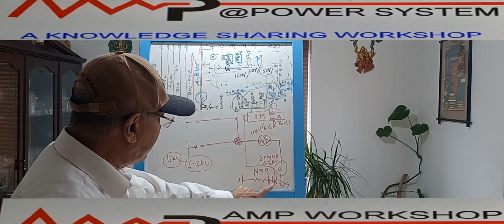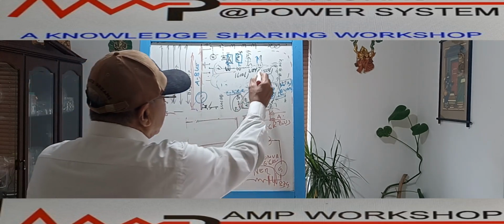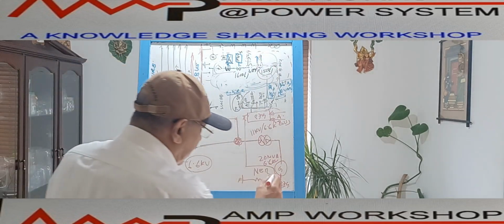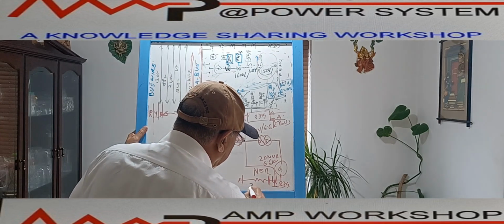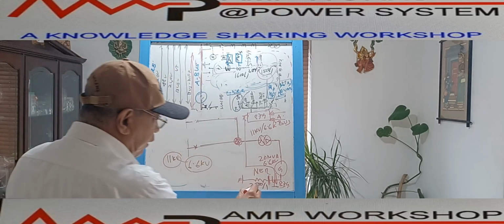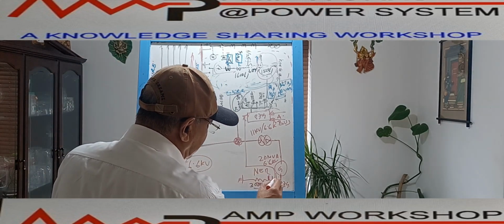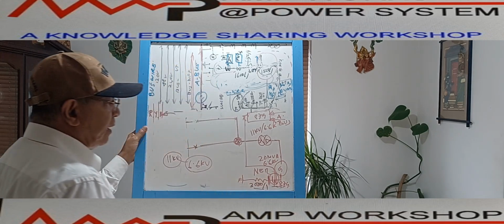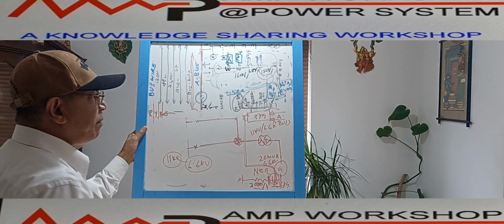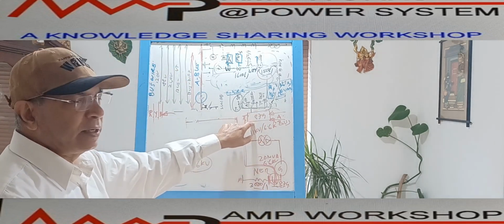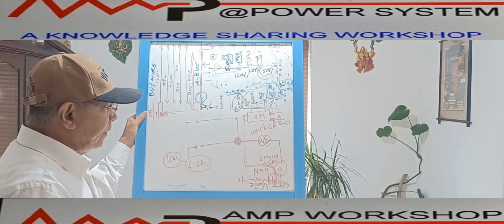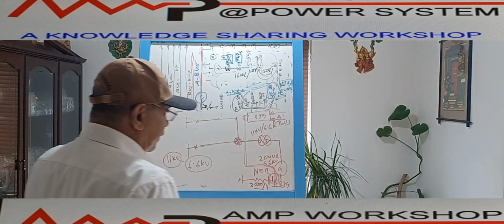As this is 6.6 kV, we have seen the feeder CT is 1500 by 1 ratio. So here the neutral side CT will be 3000 by 1, double, as the voltage is half, the current rating will be double. So this is the 87G CT, the neutral side CT. This will come from the field to the differential relay, the generator differential relay, which is located in the switchgear B panel.